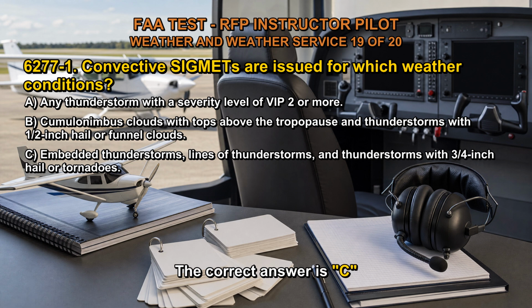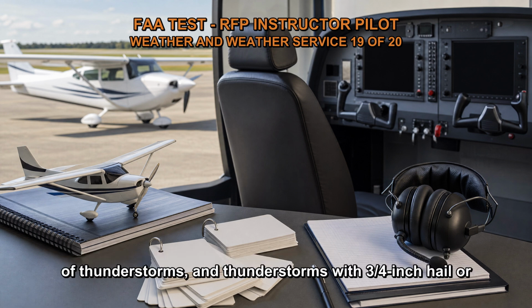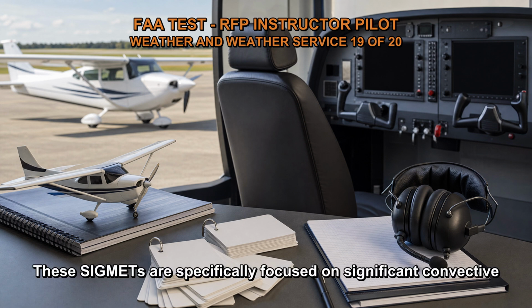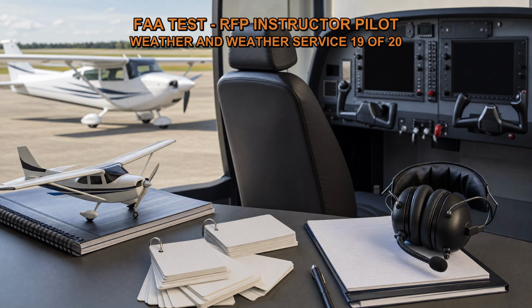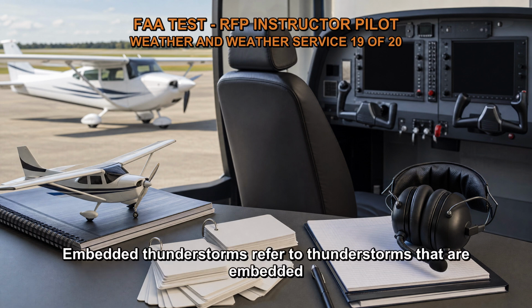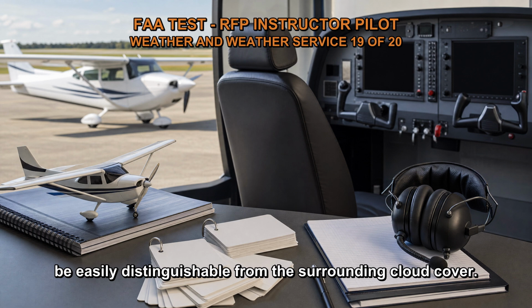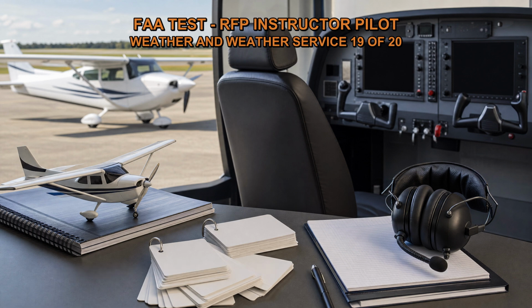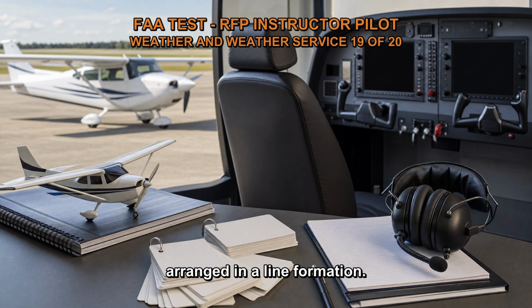The correct answer is C. Convective SIGMETs are issued for embedded thunderstorms, lines of thunderstorms, and thunderstorms with 3/4 inch hail or tornadoes. These SIGMETs are specifically focused on significant convective weather conditions that have the potential to impact aviation safety. Embedded thunderstorms refer to thunderstorms that are embedded within a larger cloud mass and may not be easily distinguishable from the surrounding cloud cover. Lines of thunderstorms are a series of thunderstorms arranged in a line formation.